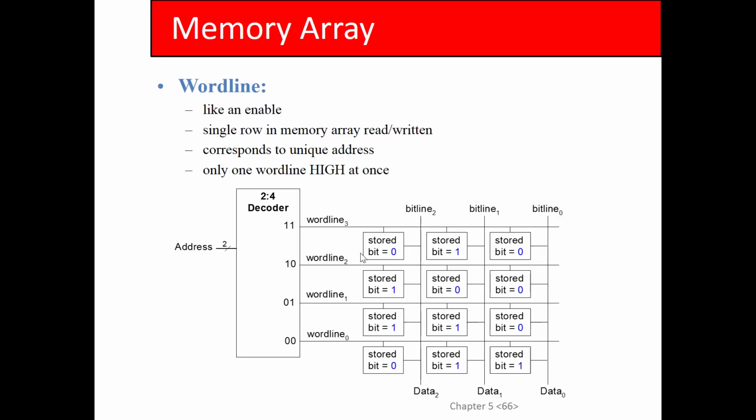So this is an example of a 4-row and 3-column memory. The word lines are generally attached to a decoder. So you put an address into the decoder. This is a decoder in the classical sense, where you put in an address that's binary encoded, and then this is converted to a unary encoding or a one-hot encoding, where there's 2 to the n outputs, where n is the number of address bits, and one of those will be activated for each address.